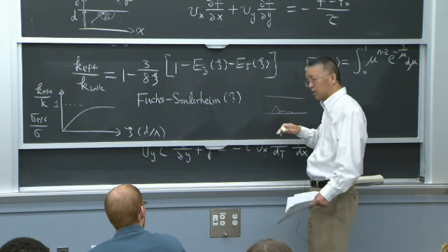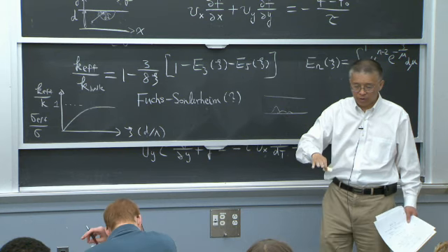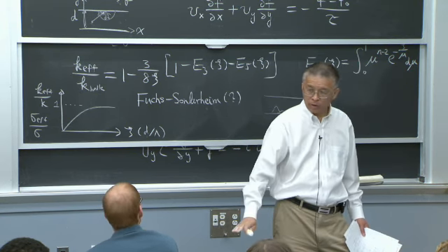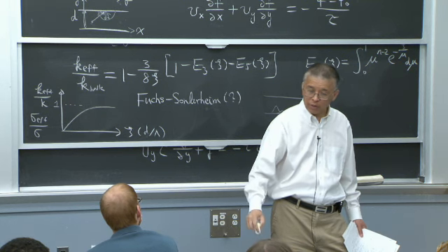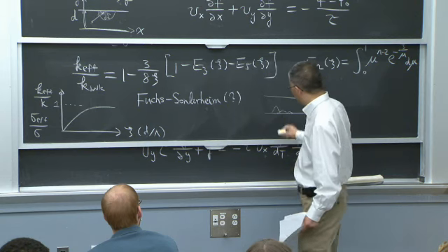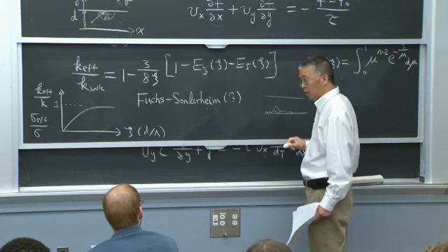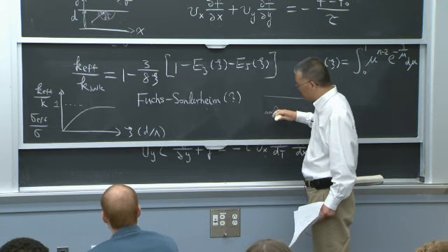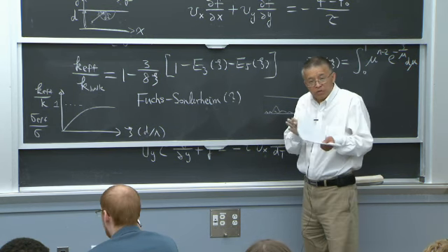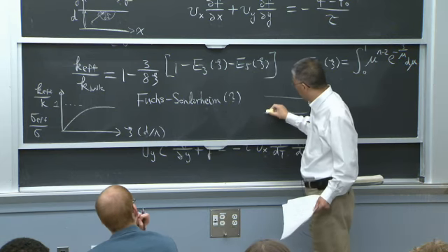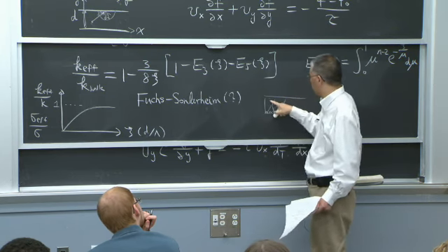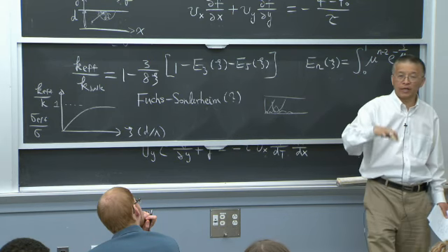When you deposit the material on top of the substrate, first you have nucleation. The atoms nucleate as small dots, so there are a lot of small crystals. When you further deposit, some of the smaller crystals disappear and the larger crystals win, so your crystals grow larger and larger. So the grain size is not constant.